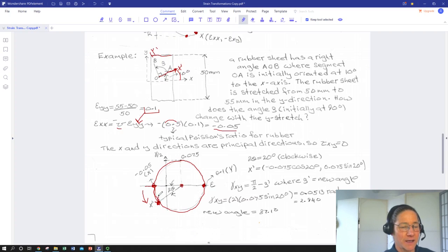So I can basically establish the shear and the normal strains by simply taking cosine and sine of that 20 degrees and multiplying by the radius of the Mohr circle. Just use right angle trig. So this distance is going to be r, my marker quit, r sine 20.